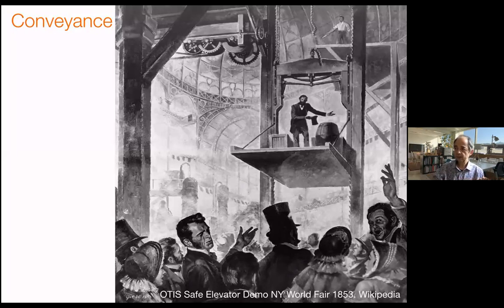Very few times you will use escalators. Escalators are very energy consuming and very expensive, but in large affluence of people, they make sense. So department stores, subway, and so on. Sometimes we design escalators in public spaces and they end up abandoned because people do not use them so much, and maintenance and power are very expensive. And often they get abandoned or just closed or stopped.